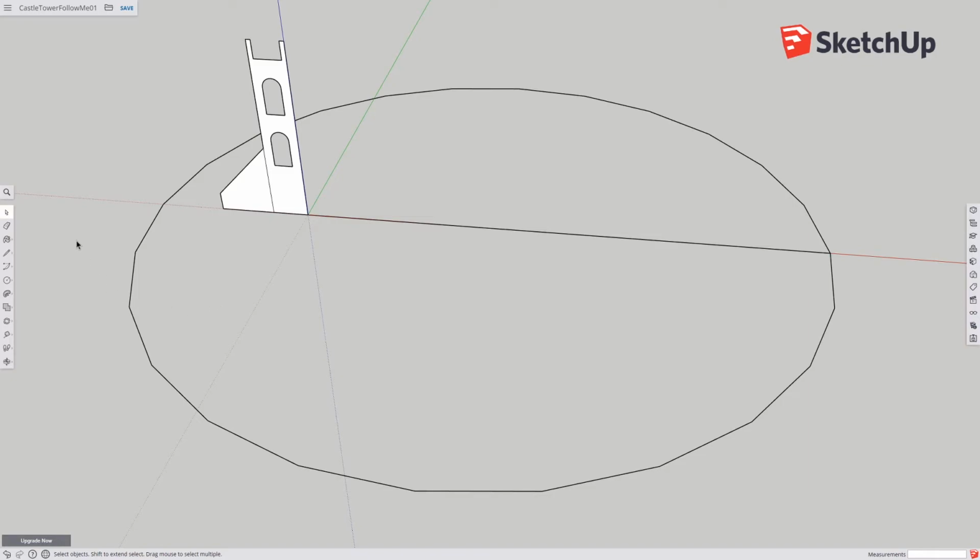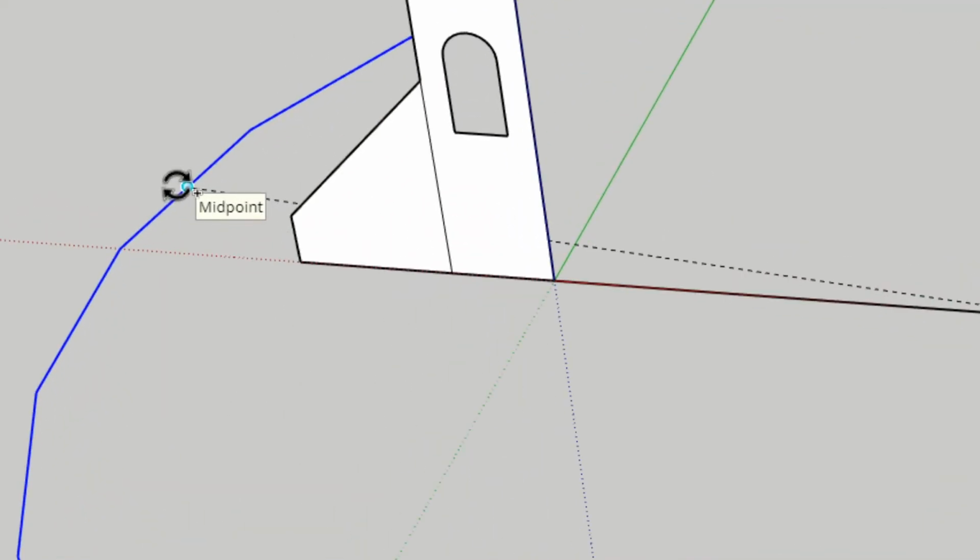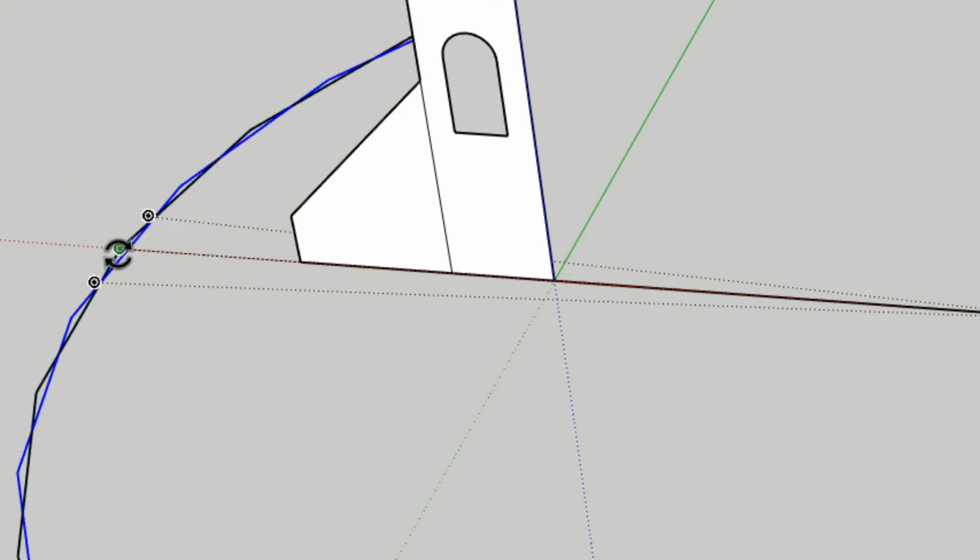Okay, so remember, if I come from the left, everything that's fully in the box will be selected. If I come from the right, everything it touches, and that's a complete path. So rotate, find my center, drag it along. That endpoint should be the midpoint, because that's where I brought my 10-meter line out and then I rotated around that. So I'm going to go to that endpoint, come along here to that midpoint. When it looks like that midpoint, I'm going to select it and then drag it to that red line.